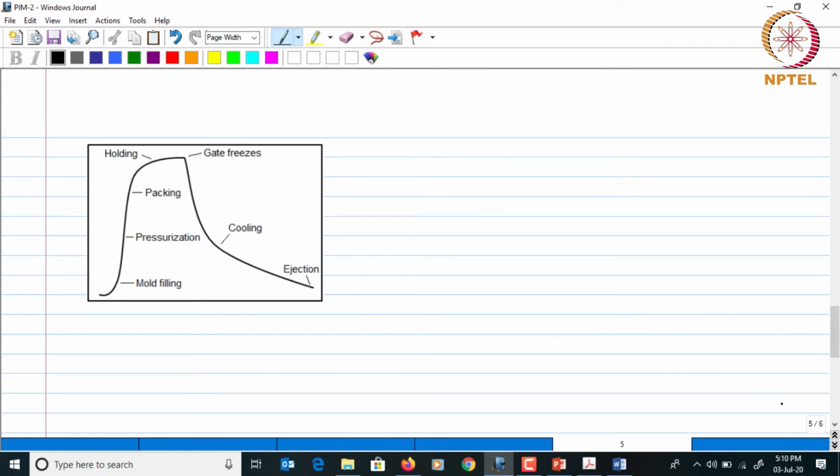Now, successful molding also requires low viscosity, as I said before, and viscosity will depend on the shear rate. If the shear rate is very high, then the powders will tend to separate from the binder and the viscosity will increase.